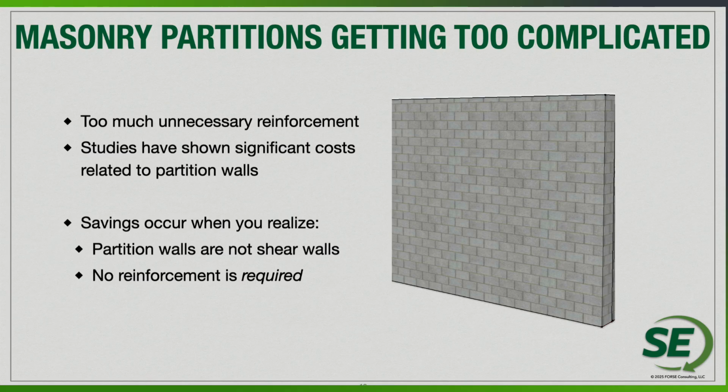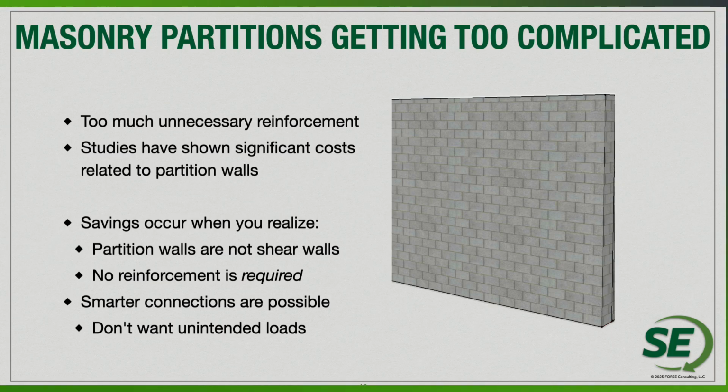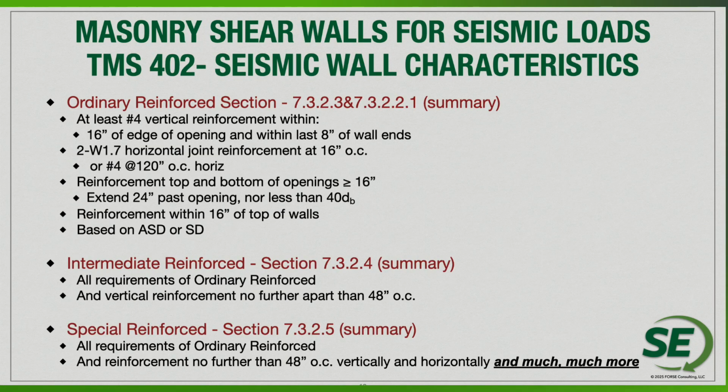If you do size them as shear walls, we definitely know that they're going to get more complicated and have a lot more reinforcement. So we definitely want to make sure that we don't have anything like this going on for partition walls. We definitely want to make sure that they're efficient elements.